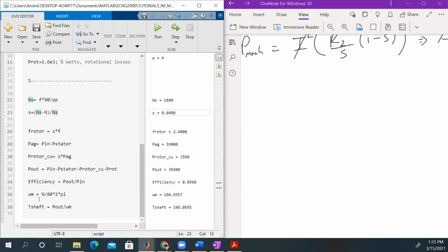Here at the output, we're not actually going from electrical to mechanical. We have the mechanical speed in RPM, and we just want to find out what that is in radians per second. So it is just a conversion of units. It is not converting from electrical to mechanical and back, right? Everybody clear on that? This is one of the tricky things that people often confuse.